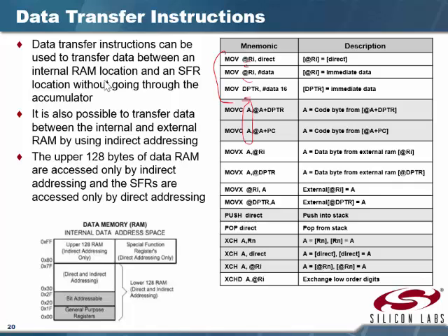That's there. Now move X, our next series of 4, which is just as versatile right there, that is talking to that external memory outside the chip that we talked about. Only in our case, with our particular processor, it's internal to the chip, but external to the core 8051. So it's on the chip, but we treat it as external. Again, we have all of the various variations of our addressing scheme. We've got direct, indirect, indexed, immediate, all those are there.